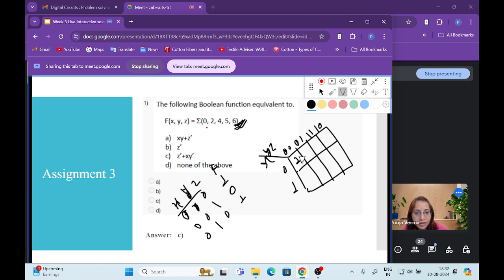Okay, right? It is the representation of 0, 1, 2, 3, and the rows and columns are arranged in Gray code. Always remember this. That is why it is 0, 0, then 0, 1, and it is not following the binary sequence; it is 1, 1, then 1, 0, because it is arranged in Gray code sequence. We will see it. I have one question on that. That is it.